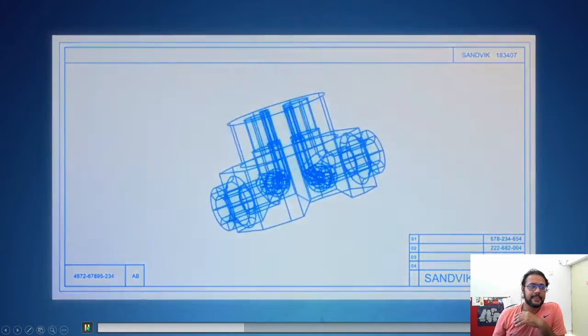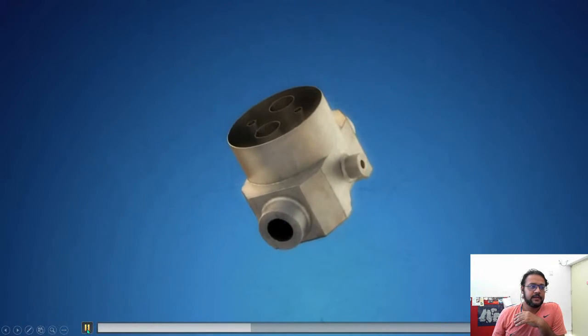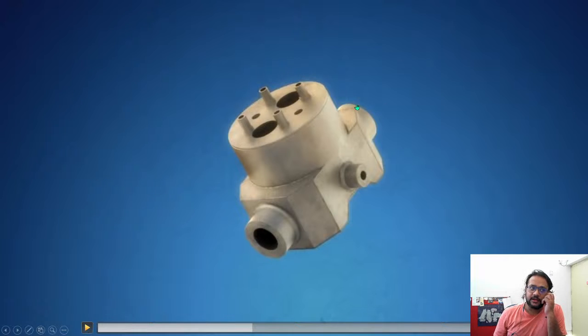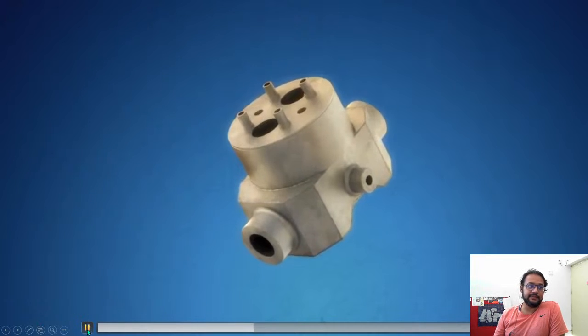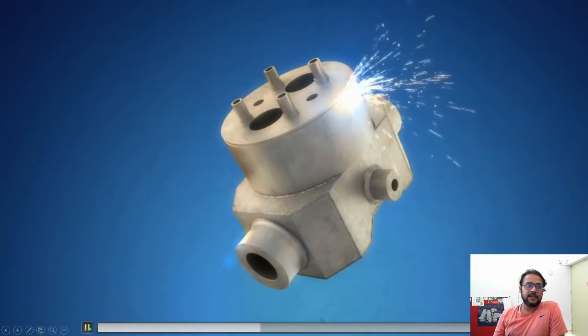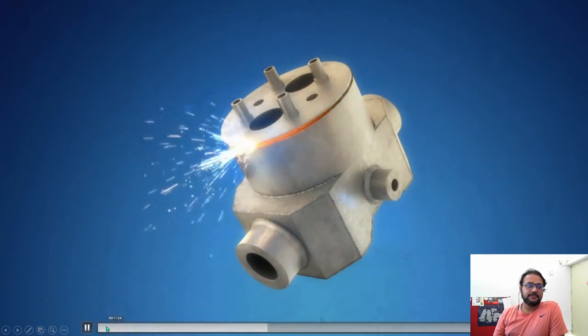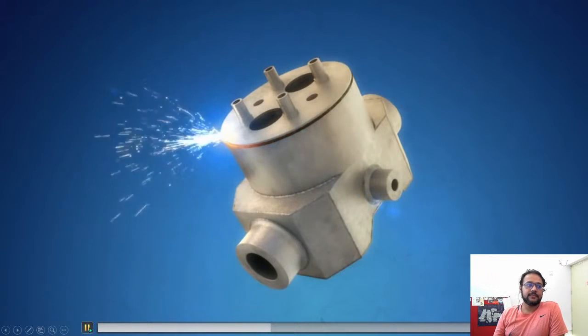Manufacturing HIP products with irregular shapes and complex geometry offers several advantages compared to castings. So you saw this is like a sheet metal shell made out of various parts welded together, and these kinds of weldings need to be perfect because of the process that is done later on. The capsule is made by forming and welding sheet metal. The tightness of the finished capsule and its welded joints is verified by testing with helium gas.